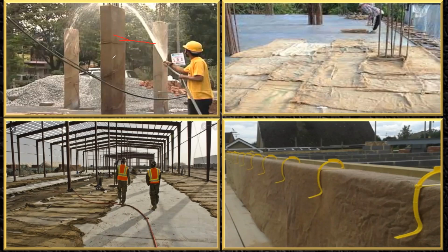You just have to spray it in the morning, so that it will remain there for around 3 to 4 hours. Then again in the afternoon or evening, you have to sprinkle the water on the gunny bag. You can practice the same for the slab also, but for the slab we usually go with ponding only, because if you're going for the slab with the help of the cloth, then you require a huge number of these gunny bags. So again, it's not that easy. It is better to do ponding for that.